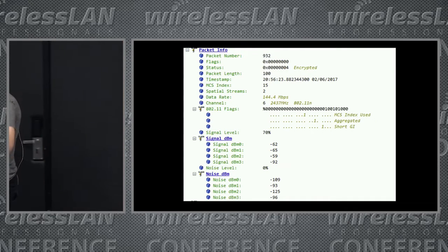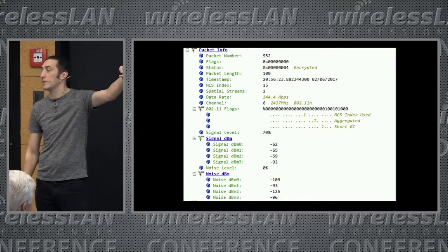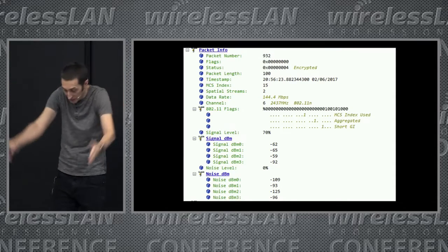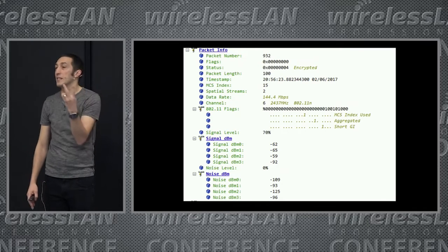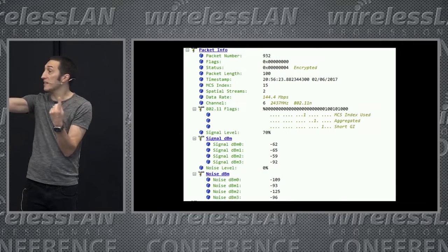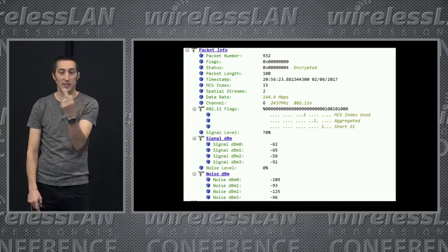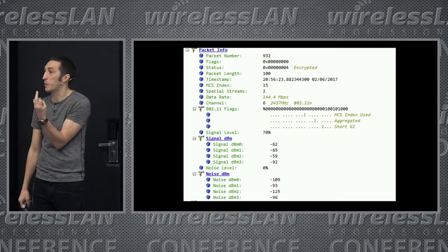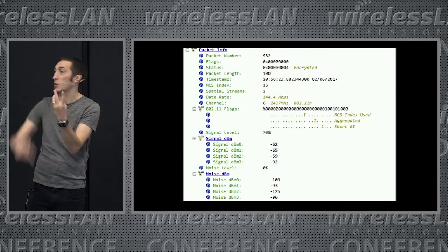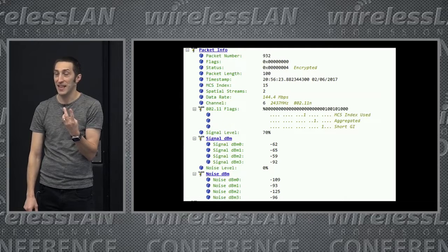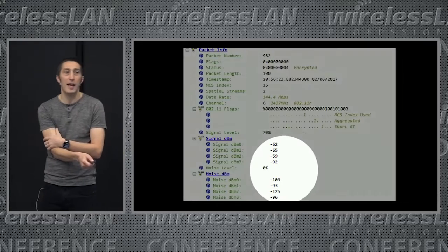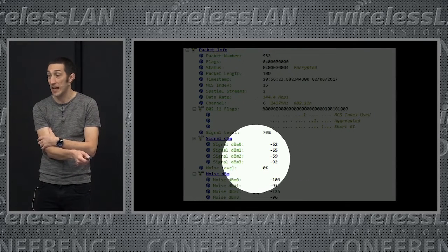Well, let me go back to thinking about I'm transmitting 2. If I'm sending 2 spatial streams, I'm going to send one from one antenna, one from another. A receiver, let's say they've got 2 antennas. What do we receive on the first antenna? They receive both signals, don't they? A combination of both. On the second antenna, I'm going to receive a combination of both antennas. So effectively, I've received 2 signals on one antenna, 2 on the other. That's 4 signals. And then I compare the combination, and so I pull out these separate signals, and therefore it can give me 4 different signal readings, potentially.